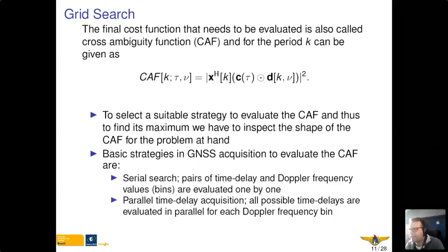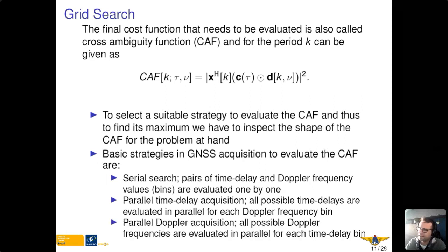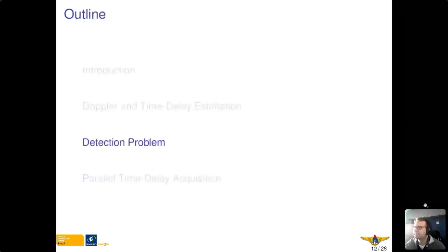Yeah, there can be parallel time delay acquisition. All possible time delays are evaluated in parallel for each Doppler frequency bin. This is the approach that we will discuss later. And there's also the parallel Doppler acquisition. All possible Doppler frequencies are evaluated in parallel for each time delay bin. So we will focus on the second method here.